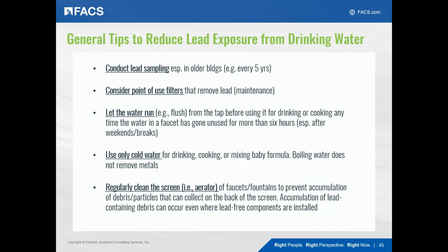Okay, so lead in drinking water is not fixed. There are a lot of factors that can influence the levels of lead. Not only the lead content of the plumbing components, right? The water chemistry, the pH of the water, the temperature of the water, the frequency of use of the fixture, stagnation, whether or not the public water system adds corrosion inhibitors to the water. So all of these factors can impact the amount of lead that can leach into the water,